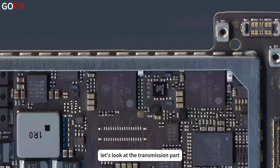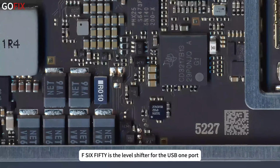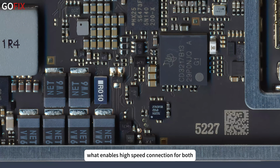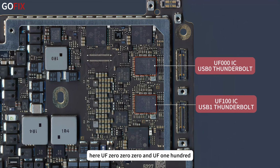Let's look at the transmission part. UF600 is the level shifter for the USB 0 port. UF650 is the level shifter for the USB 1 port. What enables high-speed connection for both USB ports is the Thunderbolt chips located here, UF000 and UF100.